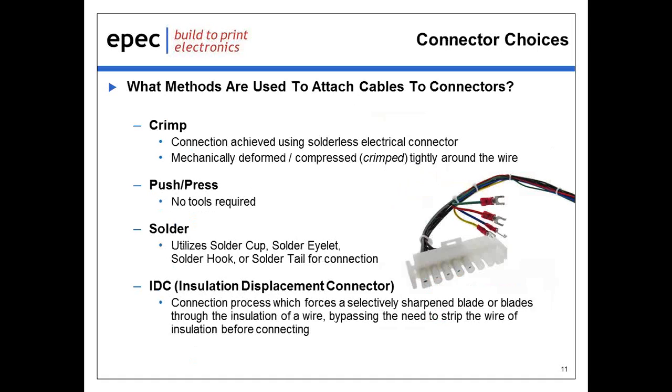An assembly has several parts that are all important. We talked about the cable portion of an assembly, and what goes on the ends of the cable is equally important. The connectors at the end are actually the point of contact between the wire and everything else. If that connection isn't very good, there's going to be a major impact on the signal going through the assembly. There are quite a few methods to attach connectors to the cable, but the method used is determined somewhat by the signal type that's going to be transmitted.